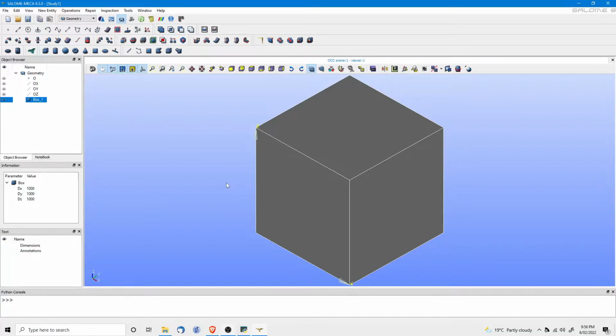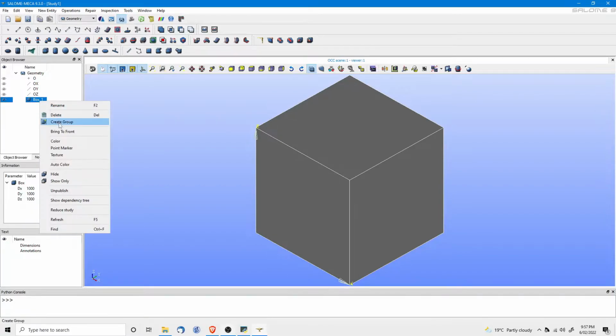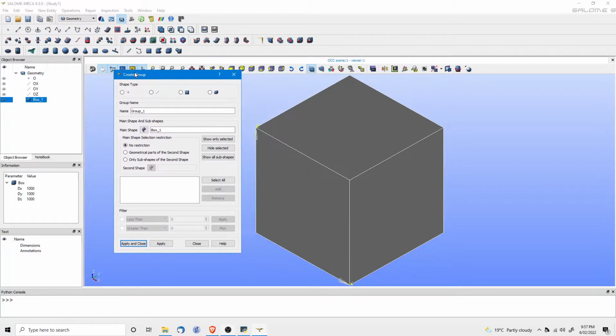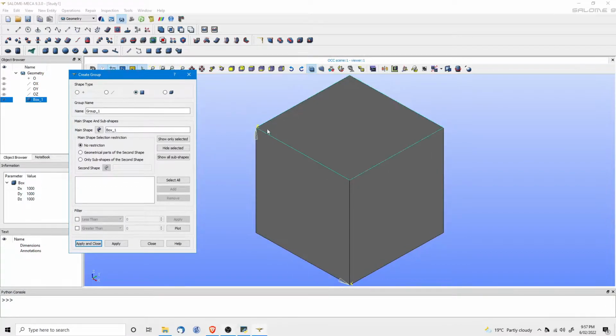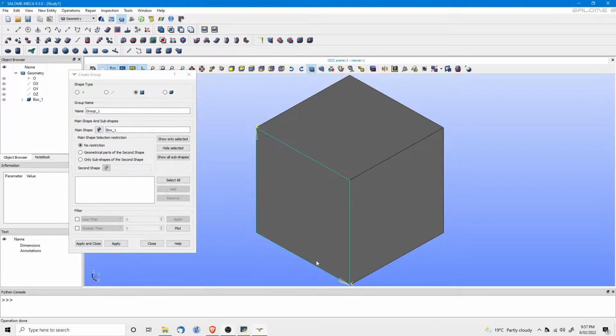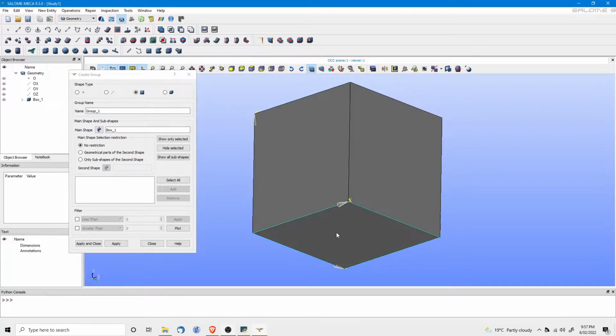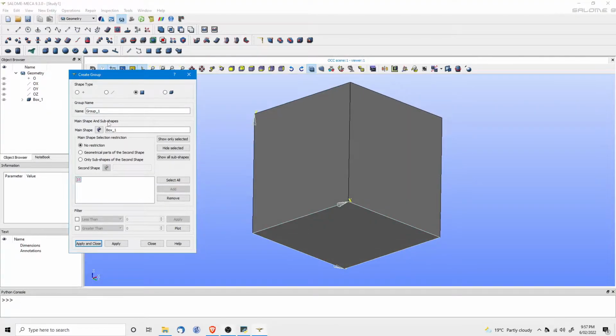The only thing that we need to do, and this will be useful for conducting finite element analysis, not just in Salome-Meca, but also in other software, which we'll look into in other videos, for example, Calculix, is create some groups. The main group that we want to create is press, or pressure, on the top face. Next, we are going to create the bottom face as DZ0.